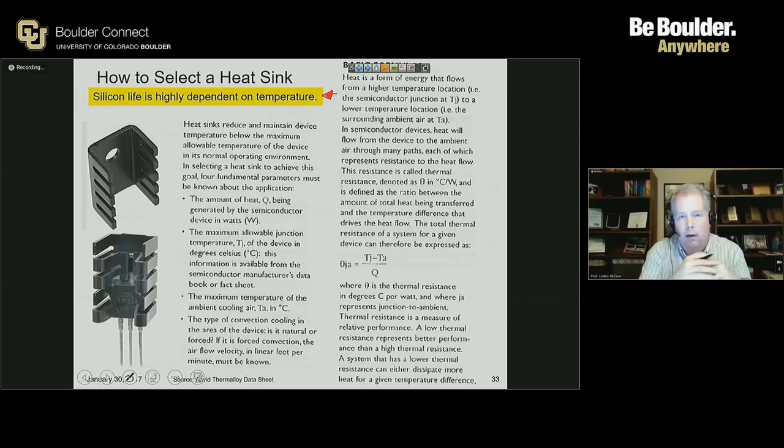So if I operate my silicon at a high temperature close to its rating, then over time that silicon will degrade and may change its characteristics some. Silicon has aging effects, and it changes over its life. But if I can do a better job at keeping the silicon operating at lower temperatures, then I extend its life and I don't stress it as hard.